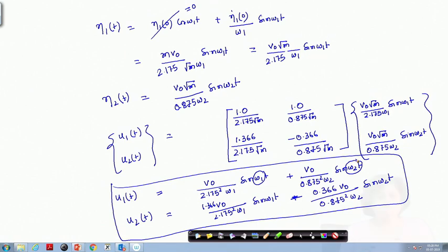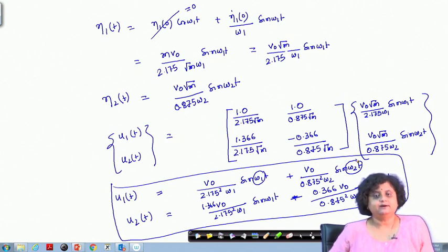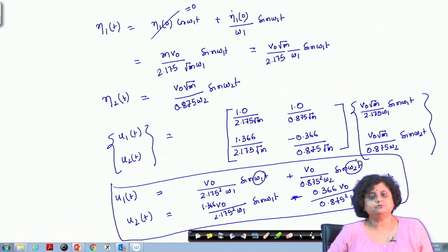So, it can be summarized that if we consider the free vibration problem of a multi-degree of freedom system, then each of the degrees of freedom of this system is going to vibrate as a combination of several sinusoid functions, each sinusoid having one of the natural frequencies of the system.